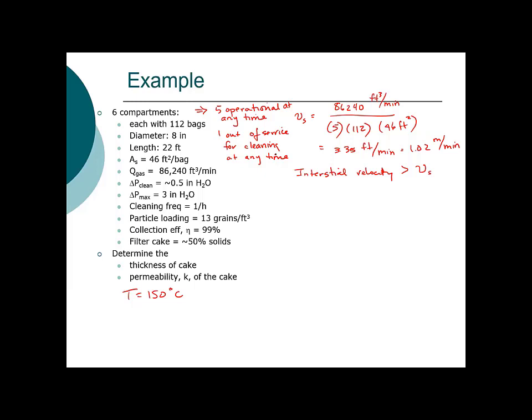The same is true in groundwater systems with Darcy velocity. So when we look at the fabric, we've got 46 feet squared. But here's our flow through this. So here's our Q. The issue is that gas can't flow through all of that material, because if we were to look at this microscopically, remember, we've got pore space.